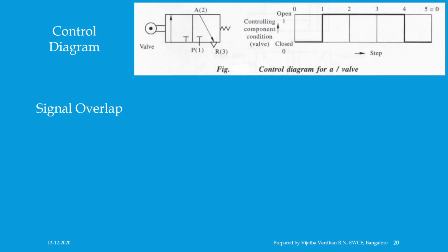In such cases, the signal of higher intensity must be eliminated or made ineffective if the signal of lower intensity is to be effective. This is a common phenomenon in valves actuated by two signals, and methods have been evolved to eliminate the signal when not required or to make it effective when necessary.